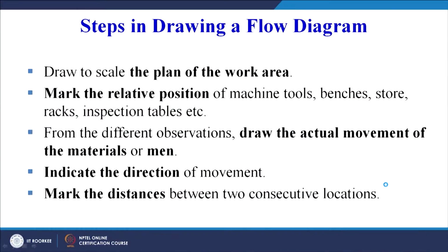Now these are the steps I will read for you. If you have understood, it is easy for you to draw the flow diagram. Draw to scale the plan of the work area, or draw the area in which you want to draw the flow diagram. Mark the relative position of machine tools, benches, store, racks, inspection tables, etc. So you mark all the facilities within the working area, that is the area that you have identified.